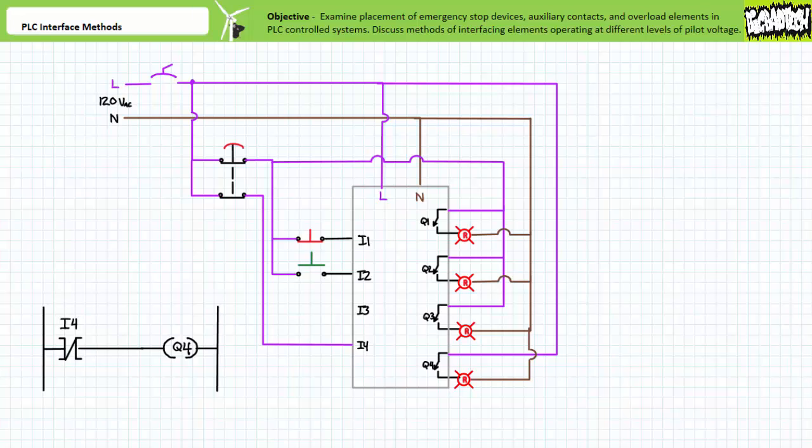Given this condition, the PLC is at liberty to direct the operation of this system with the rest of the program. If, however, the e-stop is in the activated open condition, most of the field input and output devices are disabled, input 4 and output 4 being the notable exceptions. In this condition, input I4 would experience a logical 0, and the break instruction examining input I4 does permit logical continuity onto output Q4.